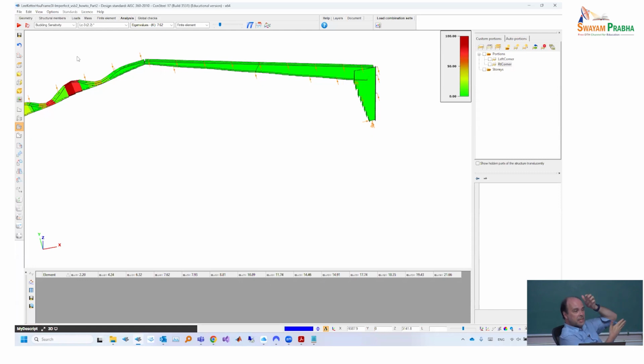This assignment is an automated process. It helps the engineer to have good advice on the buckling mode to use. You may always override this assignment if you want, but based on our experience, this works extremely well, especially considering the fact that these buckling modes typically have a very local relevance anyway. So it doesn't really matter how much we put this scale factor, this effect disappears very quickly.